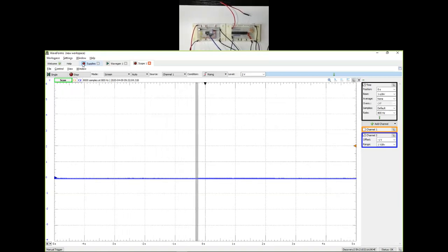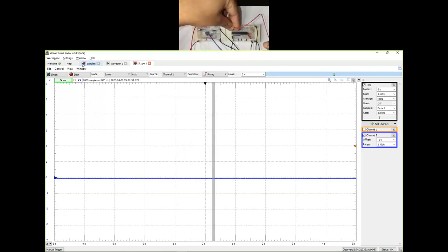And if this was a bouncy switch, if I press it one time, it is probably going to unintentionally increment through 2 or 3 or 4 times, because it's going to see several of those clock edges, which we don't want to happen. So that's why we debounced it. Our goal is to increment the count indicated by the 4 light emitting diodes only by 1 every time we press the switch, and not accidentally move up several values.